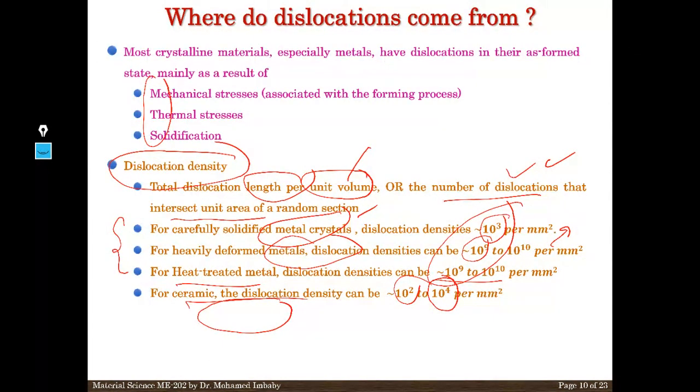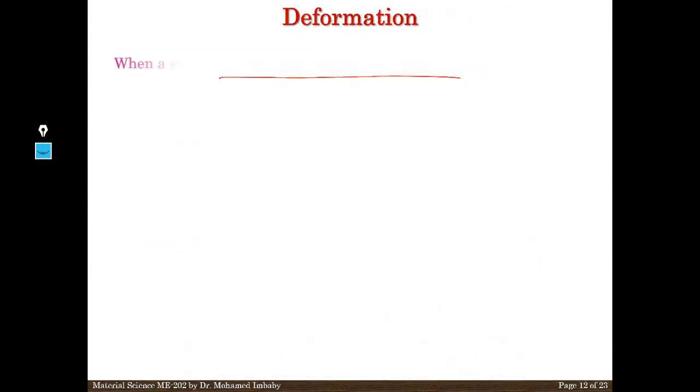And you know the metal. For example, aluminium. When you stretch the aluminium, it will be stretched and deformed, right? But when you try to stretch the ceramics, it will break, right? Yes. That is why, because the ceramics has low dislocation inside, it cannot deform very easily like the metal. Metal has more dislocation. The atoms can move easily, but in ceramic it is not. I think the conclusion is given here. Let me move forward.